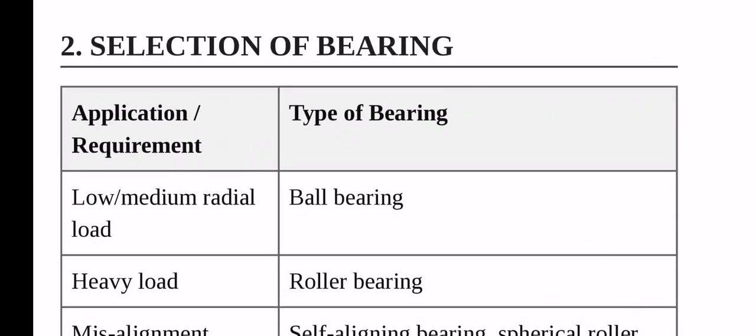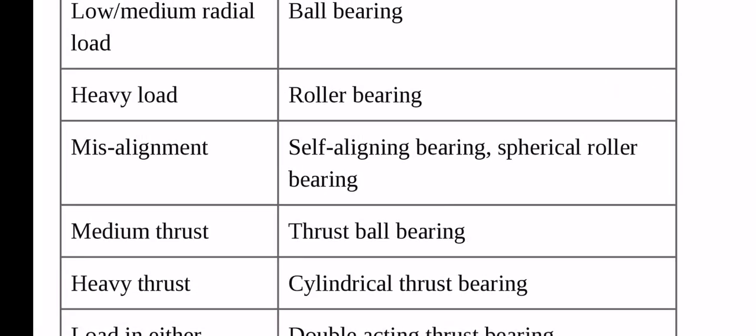Selection of bearing. Application requirements and type of bearing: for low or medium radial load, ball bearing; for heavy load, roller bearing; for misalignment, self aligning bearing, spherical roller bearing.